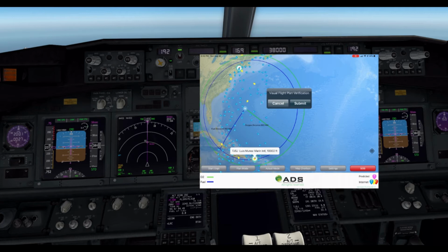This is all that has to be done to pre-flight Ergo360. Confirm the tabulated input data and then visually confirm the output data. When I click Submit, the iPad will center around the actual iPad location, indicating we're ready to go flying. Remember, the range rings are based on low-level flight and will track now with the actual aircraft position.